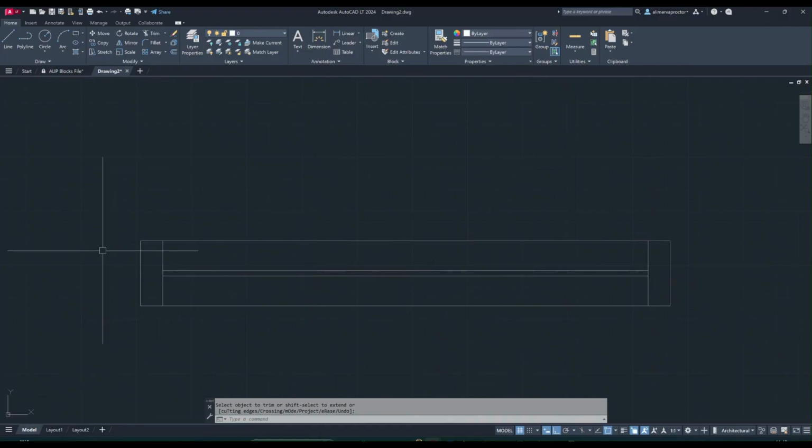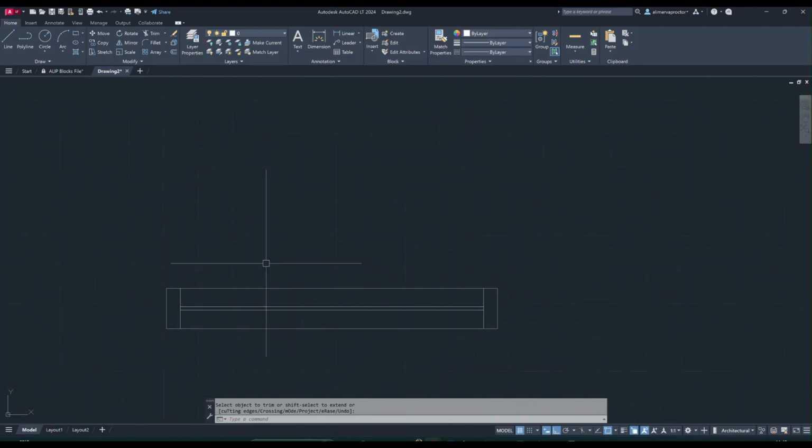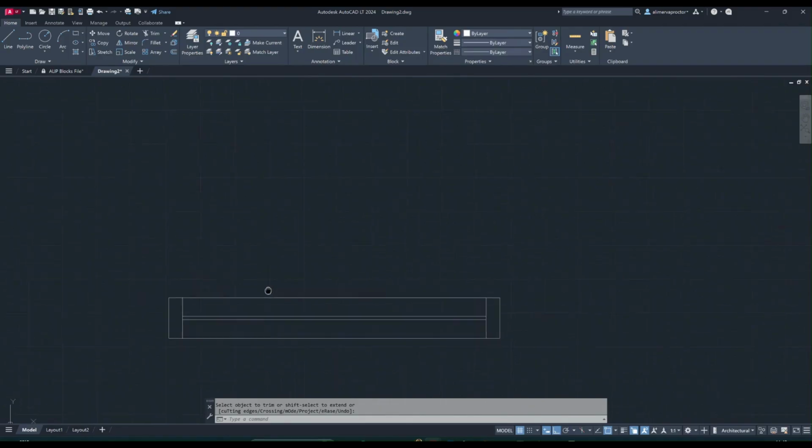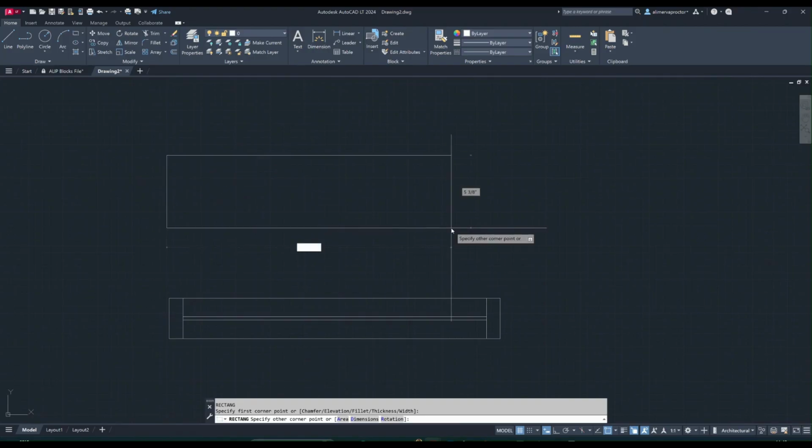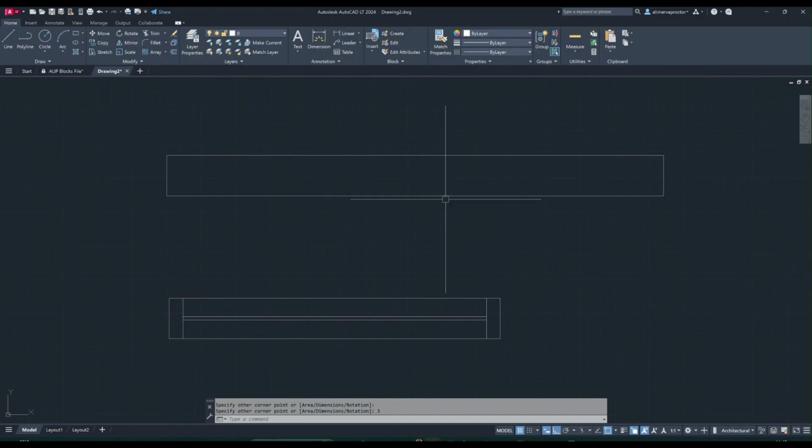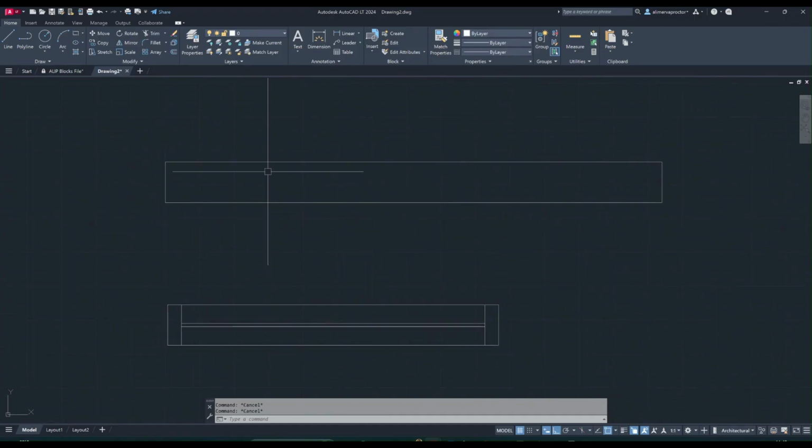Alright, so one time when we're doing this, we're gonna just make another one for ourselves that is 3 feet, right? Then we'll make them into blocks. So the same thing again, we'll try it, REC. This time we'll do 3 feet, tab 3, right? Because this one we're creating a 3 feet one, right? Once again, line, enter, from the middle point to the middle point.